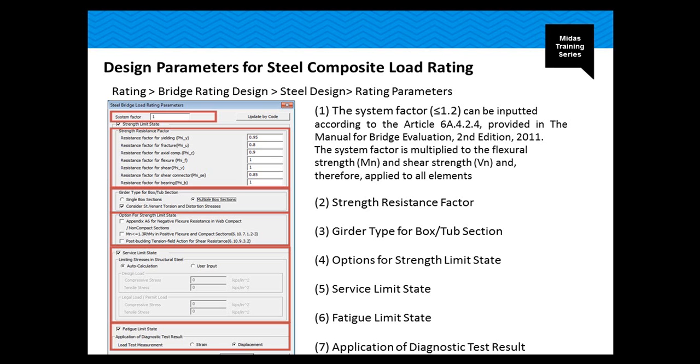Then you have the fatigue limit state application, where you can apply the diagnostic test result, whether it's measured by strain or displacement. So these are the parameters for the steel bridge load rating,